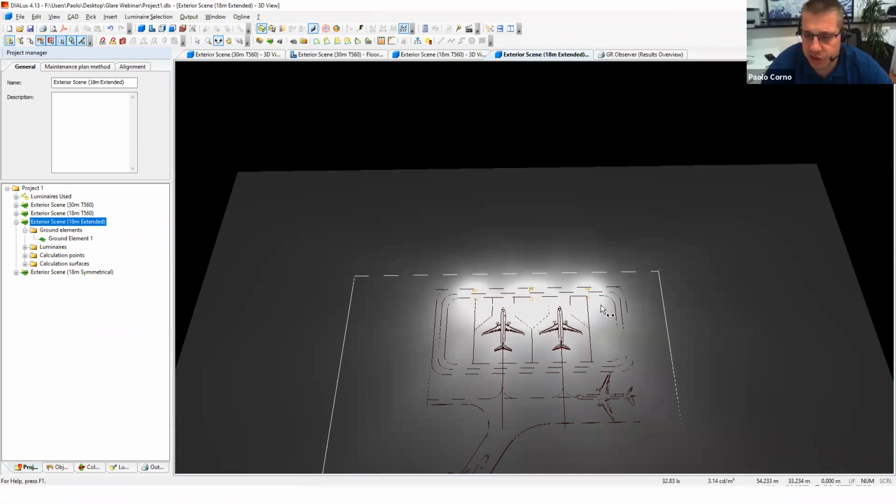which will state that if you're less than 300 meters away from a taxiway or a runway, your ULR has to be 0. Then it will give a little bit of allowance of ULR as you go further away from the runway. But that is not considered glare, because you would not effectively be glaring a pilot. You would just be confusing him. The whole purpose of that normative is to avoid pilots mistaking, when there's poor visibility, the apron lights as runway lights and then landing in the wrong place.